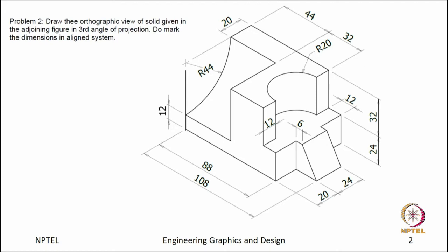Before the drawing, what I would like to mention is how to prepare a drawing sheet. For this drawing, we will be using an A3 sheet, and in the A3 sheet you have to make a box like this, where you will keep your name, units. For this figure, units are in millimeter, scale is 1:1 and this is the sign of third angle projection.